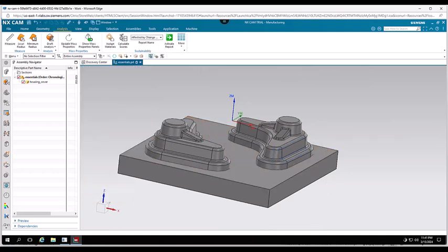Now, the last thing that I want to talk about are coordinate systems. NX has two types of coordinate systems, a working coordinate system, or WCS, and a machining coordinate system, or MCS. So the WCS is a movable coordinate system that you can use to identify geometry definitions, use them to measure with, and derive information from. You can create relative geometry, define translations. You'll use it a lot inside of NX.